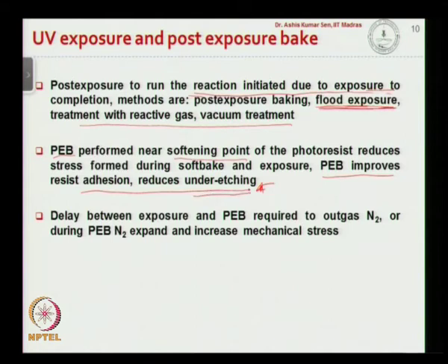Now another important thing is that immediately after doing the exposure we do not do the post exposure bake. During the exposure, because of the photochemical reaction, nitrogen is released from the photoresist. If you immediately go for the post bake, the nitrogen would expand and try to come out quickly. That would again promote delamination between the photoresist layer and the surface.